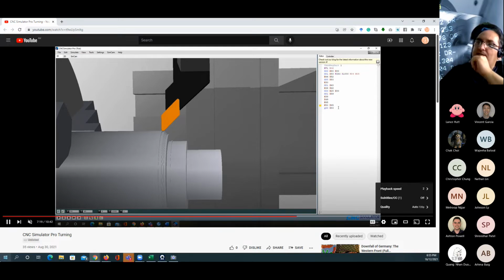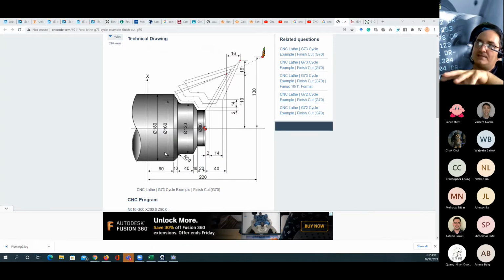As I told you, your exercise is going to be the second example we have in here. Take these dimensions, put on paper, find the points that the cutting tool needs to move to make the shaping step by step, and then at the end, write down the finishing code, which is start the work from the top to the center, or from the center to the top is up to you. Then moving all the way down, cutting the chamfer, cutting straight, cutting with the G02, you can find the radius here is 20 millimeter. And you go up and chamfer once again and straight line for the finishing operation.